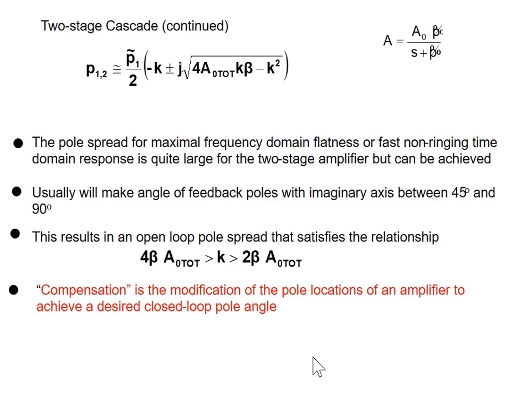That means the customer is spending a lot more power than they need to spend if they're using it in something other than unity gain configuration. Make sense? So if you're building integrated op amps, you find out what your beta is for your application, and you compensate it so that it's designed correctly for your value of beta. And many times you'll save a lot of power.